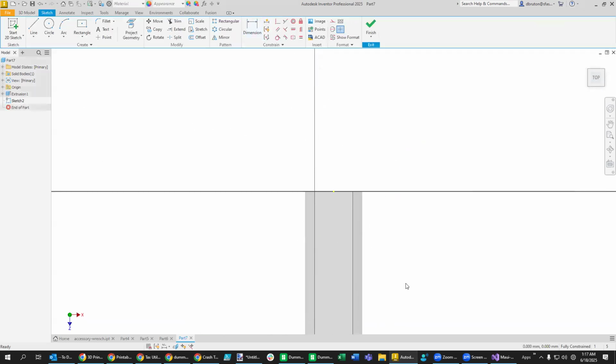Then it kind of zeroes in on one end of it, and you can begin by making a sketch on the top of that surface. Now you notice I clicked right in the center of that one. Then I'm pulling it out, clicking again, going up to my dimension tool, then typing in 8, and you got it. So if I'm going too fast on this, of course, you can slow down the video or just replay it again.